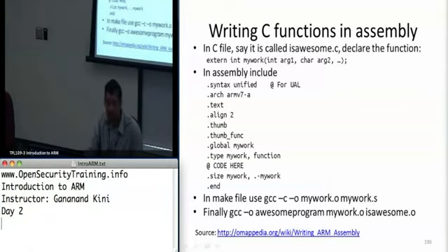The reason these come in handy is so that if you were to run this on a newer architecture, it would preserve the features of the older architecture. Generally, ARM tends to make them backwards compatible, so you'll be able to use the same piece of code. This also specifies the architecture. And since it's thumb mode, it's always aligned to 2 bytes.